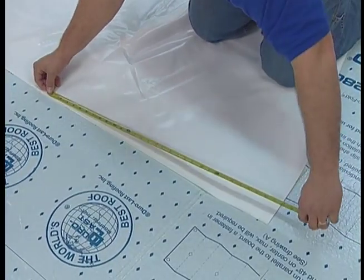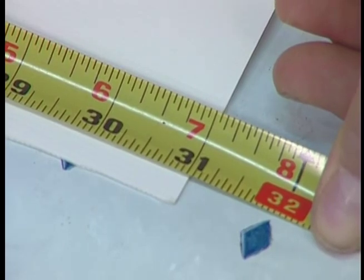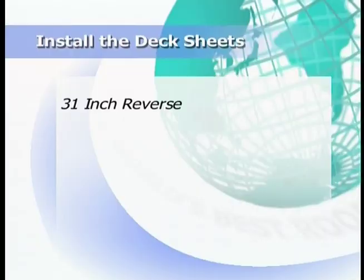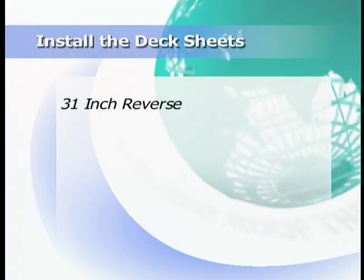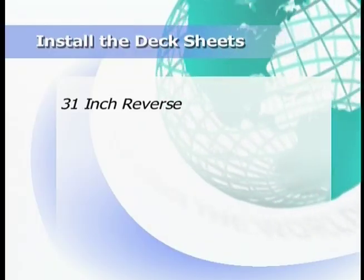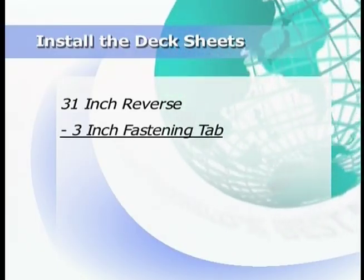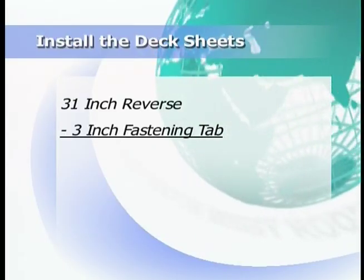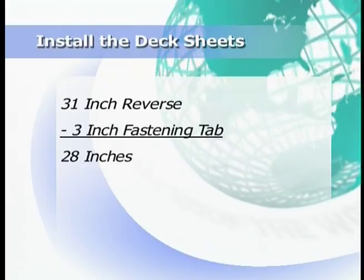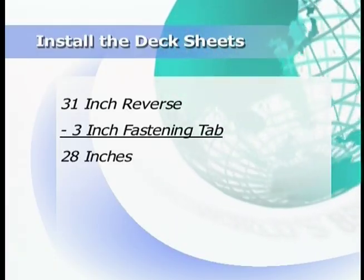In this example, we'll show you how to locate your chalk line using a 31-inch reverse. You have 31 inches from the front of your factory weld to the edge of your materials. When you snap your chalk line, you want the fastening tab to fall on the line, so you need to subtract the fastening tab width from your 31 inches. Your fastening tab is 3 inches, subtracted from 31 inches, equaling 28 inches. If you were starting your deck sheet at a parapet wall, this 28 inches would be fine.